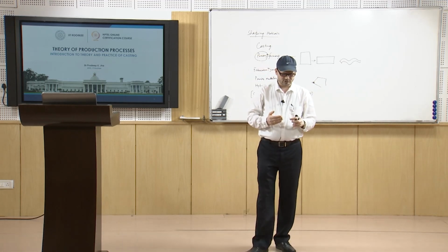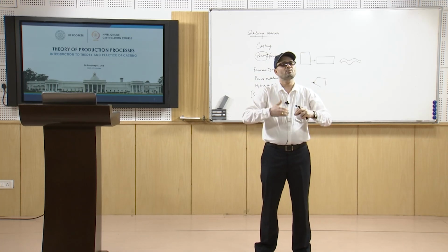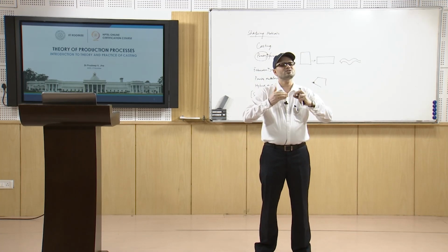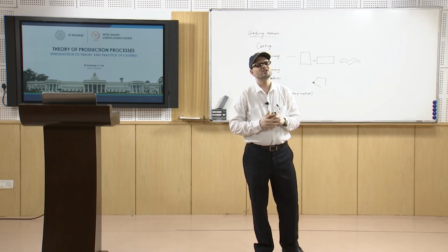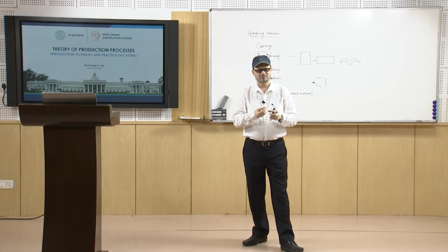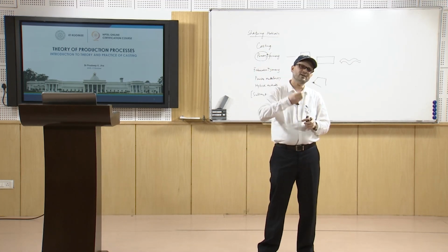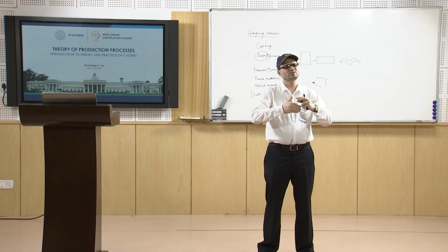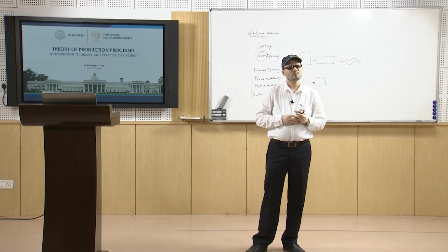and since you have the development of newer and newer materials, newer and newer processes, the intricacies, the complex details can also be achieved. You use finer materials, finer sands, you use different kinds of binders. So, this way the intricacy also can be achieved.